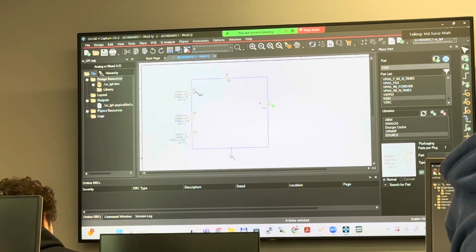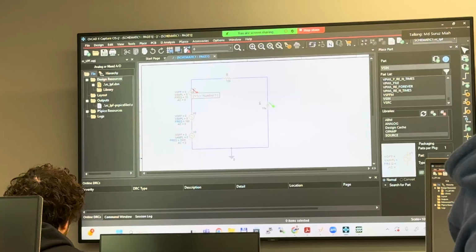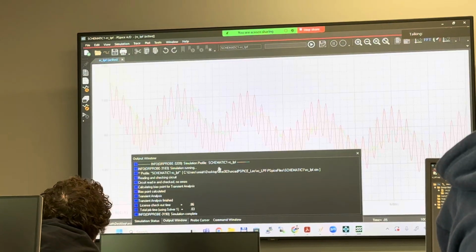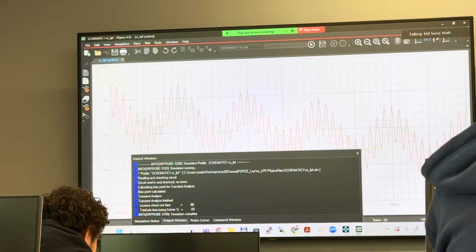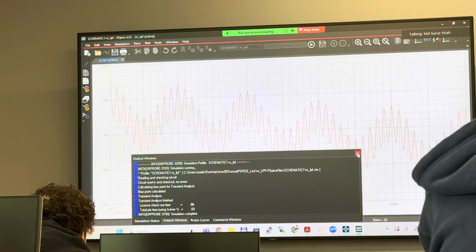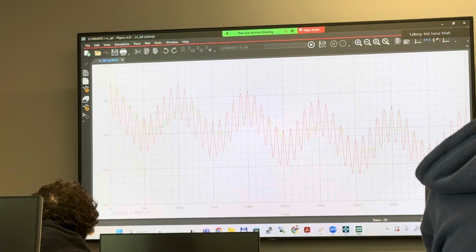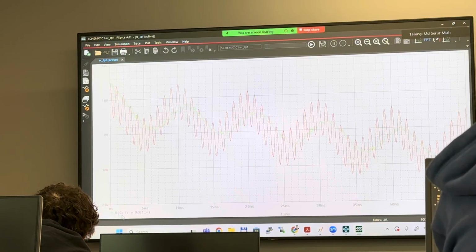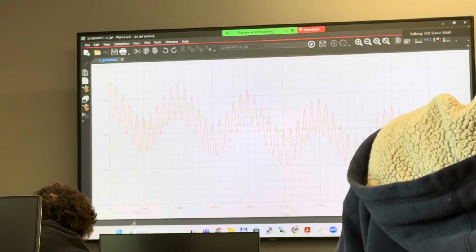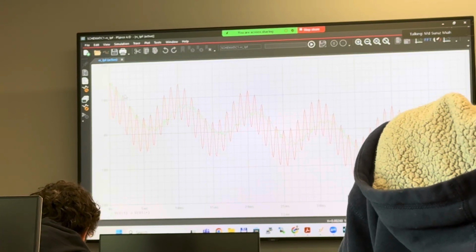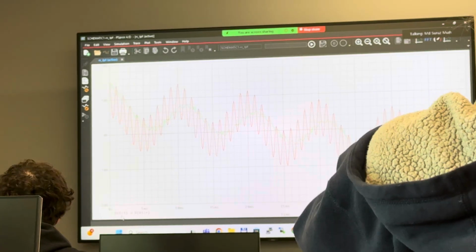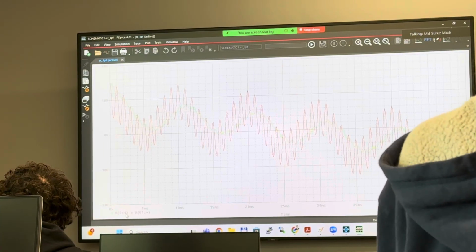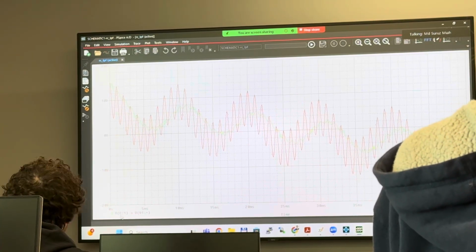And another voltage marker right here, probe, these are probes actually. Escape. Do you see? Immediately you see the input and output. And what does it mean? So here, this green, are you guys able to see? This green is the voltage across the capacitor from terminal 1 with respect to ground. That's what it means, guys.